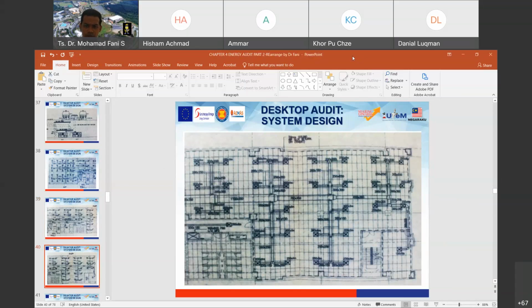And there must also be a return ducting. The return air from the room will be returned to the AHU again. At the AHU there is a process of mixing air, so we can have fresh air from outside mixed together with the return air. This mixed air will be supplied again to the room.